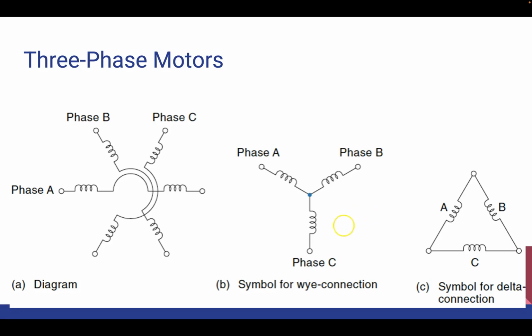And the three-phase motor can be wired to run in either direction by simply reversing any 2 of the 3 leads. For example, if the 3 motor terminals are connected to phases A, B, C, it turns clockwise. Then if B and C are reversed, the motor will rotate in the anti-clockwise direction.